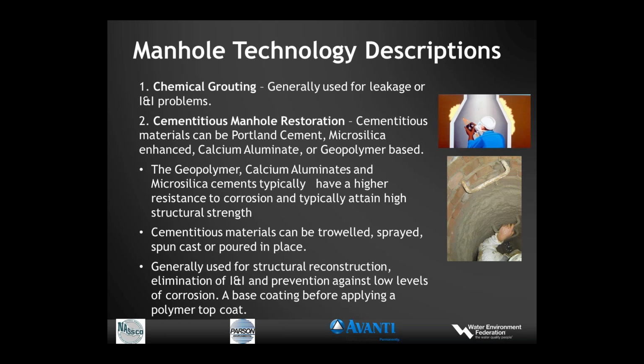Cementitious manhole restoration, as I said, has multiple different technologies out there. They're usually used for building back. They're used for, let's say, rebuilding an old brick manhole where the mortar has failed over years. We've got brick manholes in the ground over 100 years old, and in many cases the brick is fine, but the mortar has deteriorated. Well, it's a way of replacing that mortar. Corrosion is not an issue, so it's a great choice for that type of application. As a matter of fact, on an industry basis, probably 50 to 75% of manholes are still usually rehabilitated using a cementitious type of product because there's no corrosion. And once there's corrosion, then of course the other products prevail.